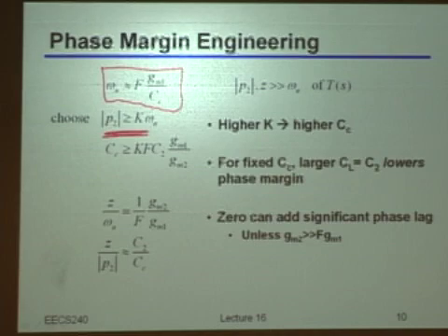Well, for instance, if you want 0.1% settling accuracy, then maybe this K factor is something like 3.3, right? So based on settling and on the behavior that you want, you decide this K factor. And that's where the second pole should be placed. But then, if you replace the expression that we have for the second pole and the expression that we have for the omega u, you get this key expression that allows you to understand how CC should be made, right?